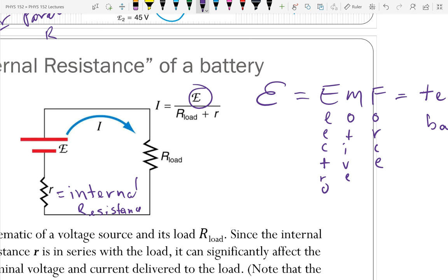But if the battery's gotten older, the chemical reaction has gone on, and like with the lead acid battery, you now have sections of that lead plate that have been oxidized, or actually turned into lead sulfate on both plates. So you have more buildup of lead sulfate, which is going to make the reaction occur less efficiently because it needs to get to either the lead or the lead oxide. And so the internal resistance rises as the battery gets older.